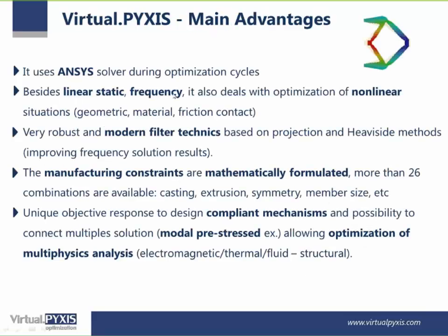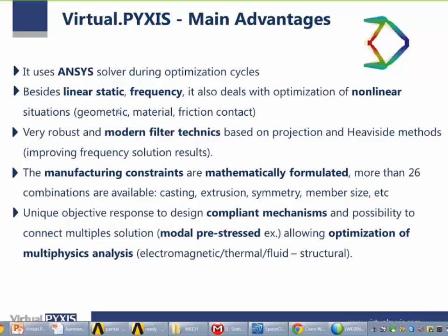Virtual.PYXIS is software integrated into the ANSYS environment. So we use the ANSYS solver during optimization. We do not use any other finite element solver for the optimization cycles. And it's suitable for linear static, frequency and nonlinear analysis, also including geometry, material or friction contact.